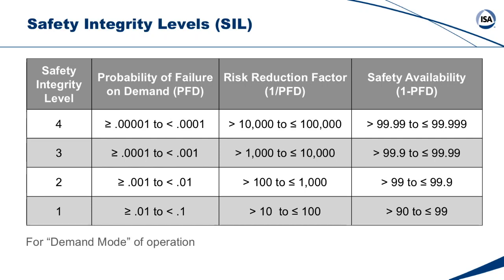I would probably say 70 to 80% of most functions in the process industries are SIL 1. The remainder are basically SIL 2. A lot of those are fired equipment, because also when you look at burner management and various standards, they have mandated for a long time redundant sensors and redundant valves and logic solvers that have certain levels of diagnostics. They're clearly stating a SIL 2 design, even though they may not have used that term in the past. Although actually now all the NFPA and various burner management standards now acknowledge alternative performance-based design. They specifically mention ISA 84. And the idea of SIL, safety integrity level.